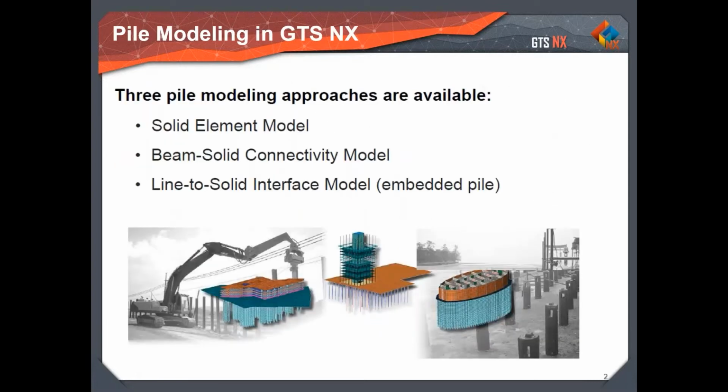Okay, so when we come to GTS NX, we can model piles with three different approaches. Actually, in general, in a 3D numerical tool, you should be able to model your pile as a volume element, and you should have a proper interface around it to be able to capture this interaction between the pile and the soil. So this is a basic ingredient you should have. In GTS NX, we can do that.